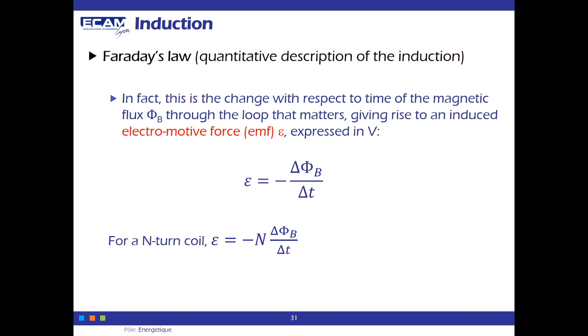For instance, people already make this for your computer charger or your phone charger. In fact, they are transforming by using this very principle, my dear friends, making the network energy, which is 220 volts for Europe with 50 hertz, appropriate and utilizable by your phone. And by using this principle, we supply 5 volts electrical energy to our telephone. Voila. And I repeat, this is exactly based on this law.